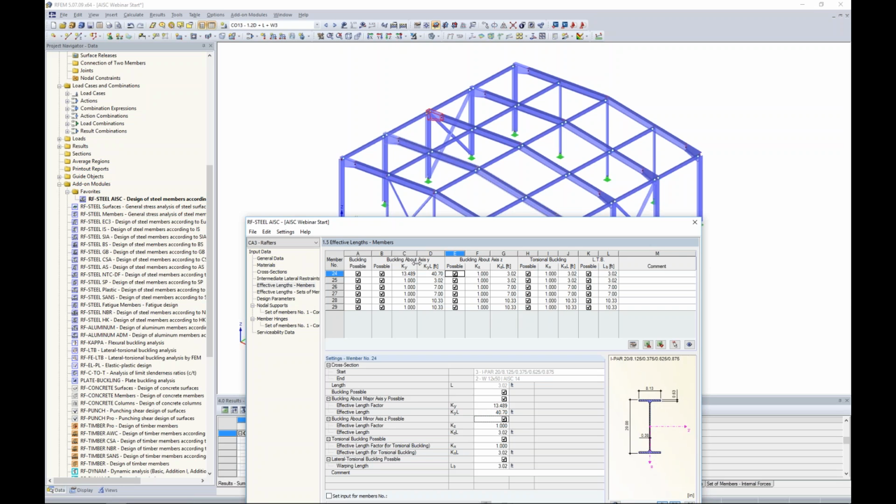At some point in the future, we will implement two separate columns here, one for K, one for L, and then a third that includes the KY times L. For now, just completely neglect that this K value is changing. That's just because our column here that's actually used for the calculations is what's important. Since our K is equal to 1.0 according to the direct analysis method, I'm just multiplying that by the unbraced length of 40.7.